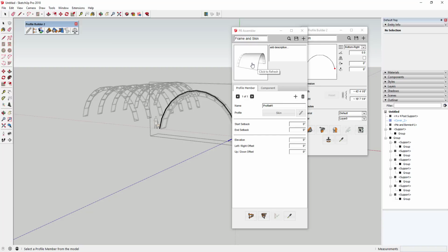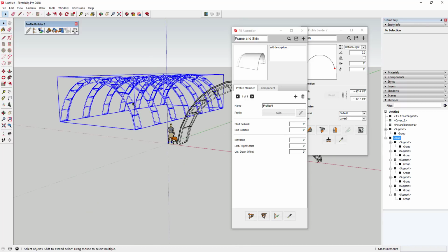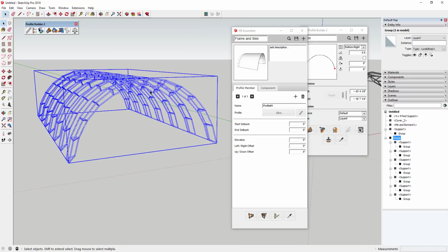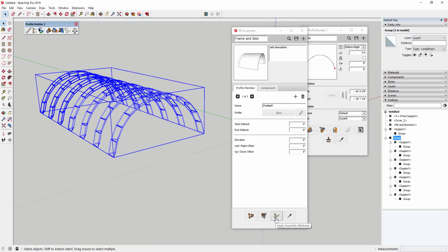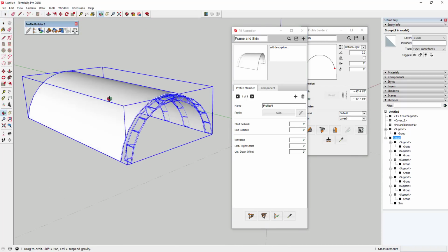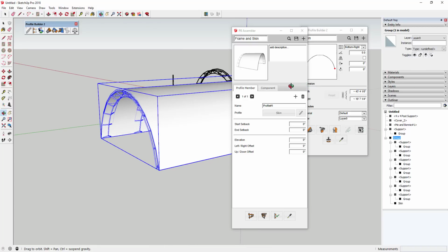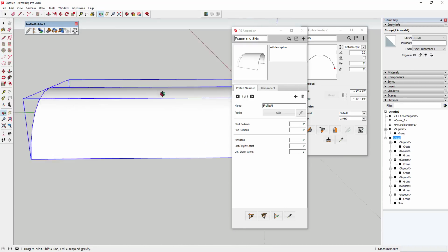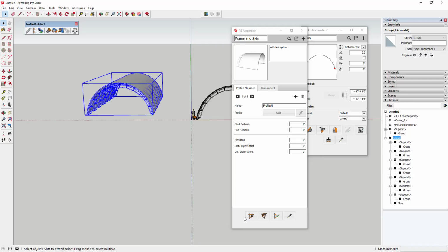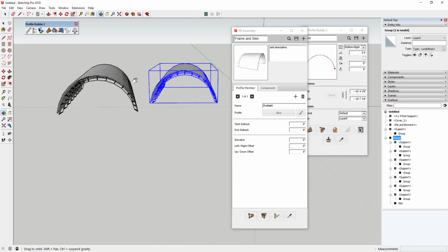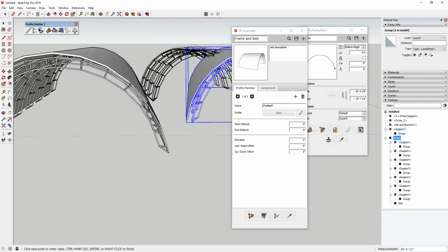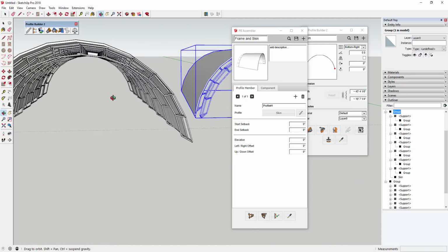So you can see how now in my preview, the skin is actually showing up in my assembly. If I click on this assembly now, select it, and then click Apply Assembly Attributes, you can see that what that does is actually generate the skin in my object. So if I was to create a new profile, that's going to generate my structure with my skin.